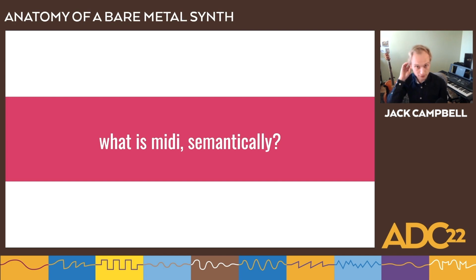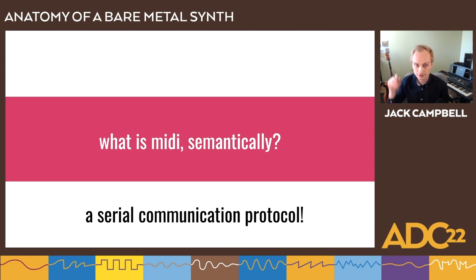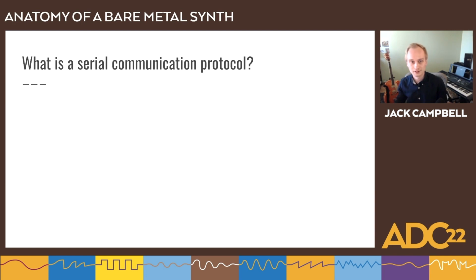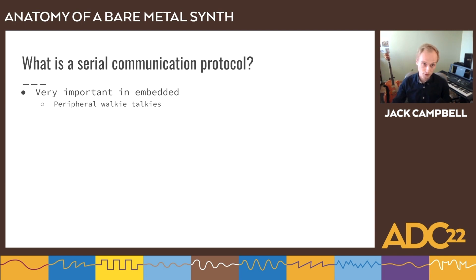So that's what MIDI is physically, but the semantics of MIDI are part of a larger embedded systems concept that will be important for just about every project that you do. It is a special case of a serial communication protocol. So what is that? It's a very important concept, like I said, pay attention. If you think about an embedded system like a series of peripheral walkie-talkies that all have their one job or their set of responsibilities, any interesting device is going to need to communicate between these